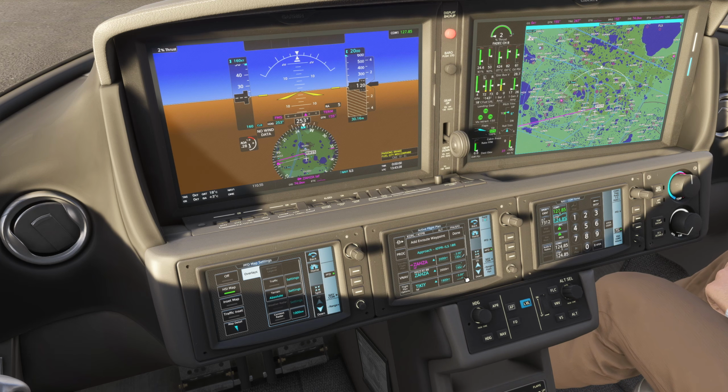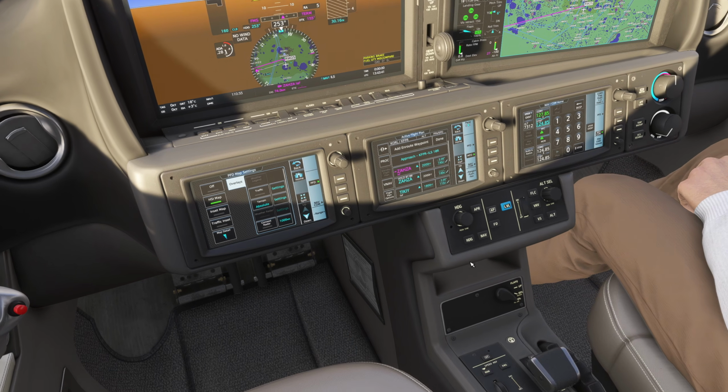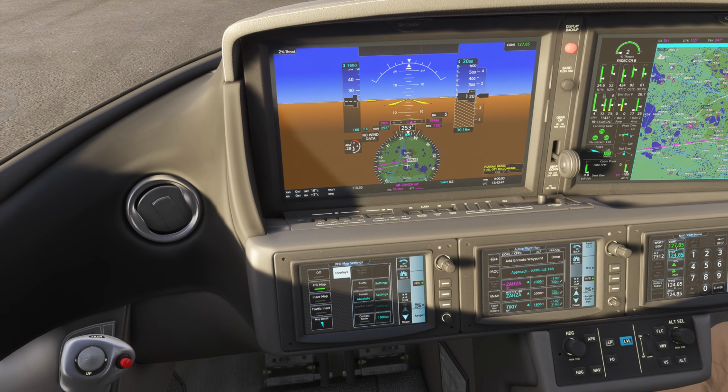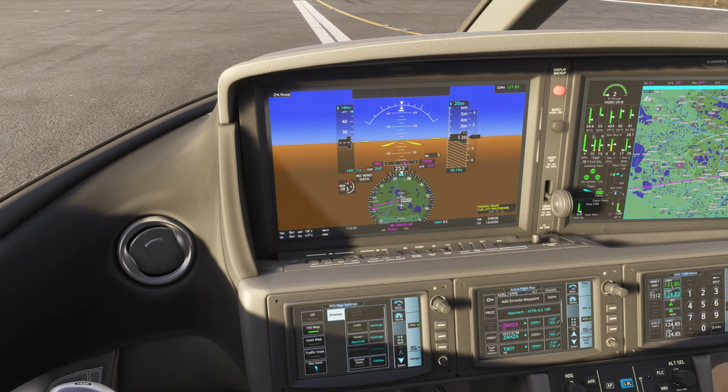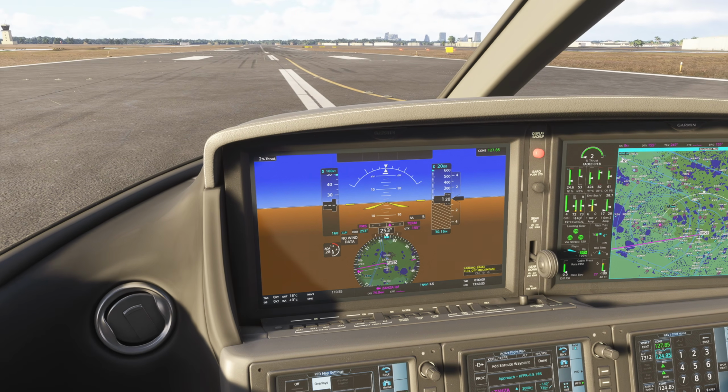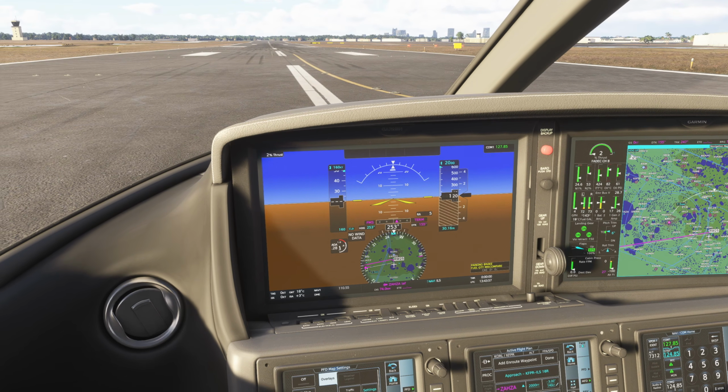So before then, I would say around the T-key, we're going to make sure we're nice and slow around 115 to 110 knots. That's a good speed. After we reach that speed, we'll manually reduce the thrust lever ourselves and try and maintain 90 knots. I'm going to write all the V speeds in the description below so you know, and we want to try and get them in our heads so when we're flying the approach, we know what speeds we should be at.